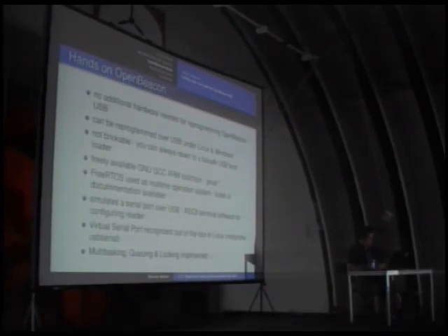Yeah, and to make it even more simple for you, on the OpenPCD project we don't use a USB debug cable anymore, but we implemented a serial port emulation over USB. So you have a very convenient serial debug interface on a virtual COM port where you can change modifications and send debug output to your computer.